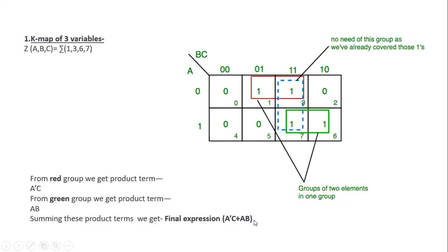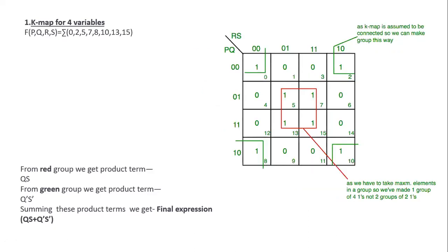Easy, right? The same way you can do it with 4 variables also. You can see the question is given with a summation sign. That means it's SOP. Here 4 inputs are there, so the maximum count has gone to 15. Now here you can identify that if there is any misprint, like the number 15 is given and only 3 inputs are given, either it will be 3 variables or 1 variable is missing. Fine. So that is how you will come to know whether there is any mistake in the question.